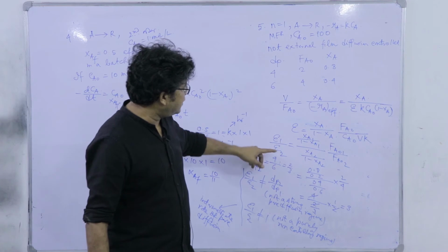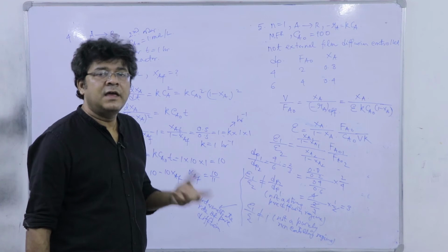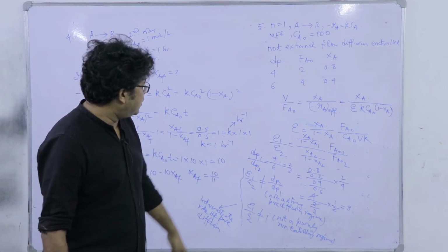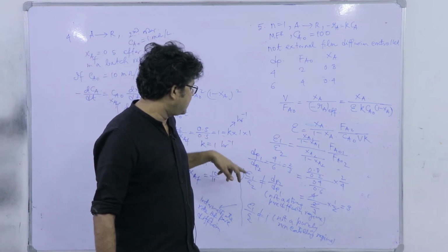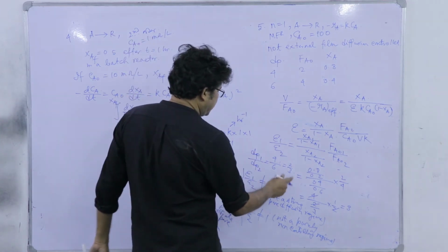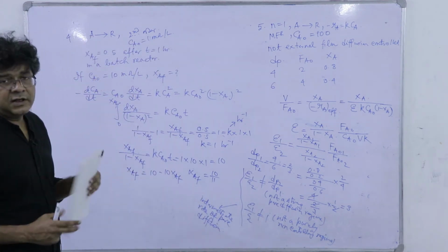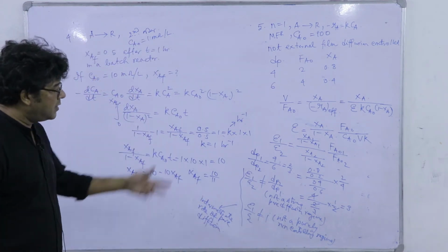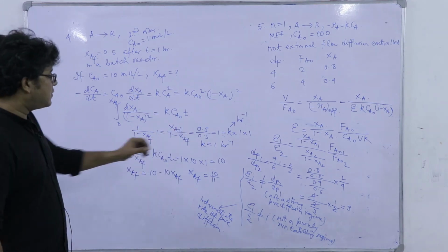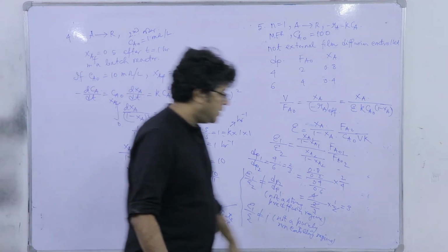And epsilon is not satisfying this proportionality with 1 by mt, that is the Thiele modulus, and mt is proportional to L, proportional to dp, right? So dp1 by dp2 is not equal to dp2 by dp1, 3 by 2. So this is not the same. Additionally, if it is reaction controlled, both the epsilons will be equal to 1 and epsilon 1 by epsilon 2 must be equal to 1. That's not happening either, right? So we can conclude that this is an intermediate role played by pore diffusion.